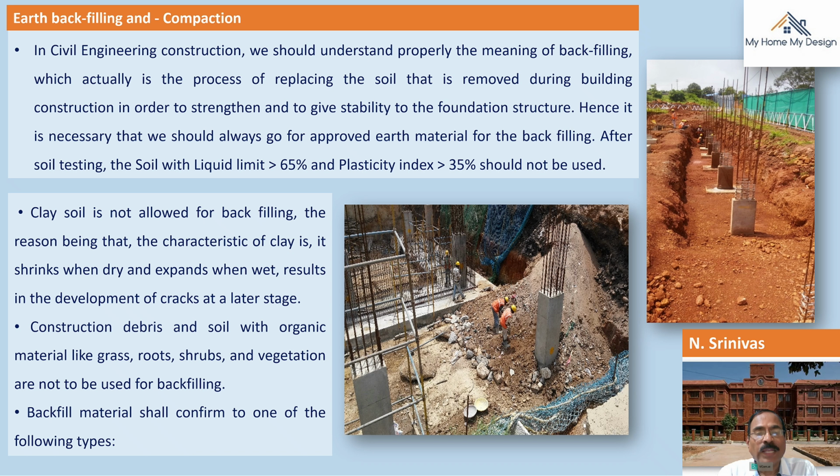Now, clay soil is not allowed for backfilling. The reason being that the characteristic of clay is it shrinks when dry and expands when wet, resulting in the development of cracks at a later stage. Yes, what is this clay soil? In Kannada, we call this clay soil as JD Mannu. It shrinks when dry and expands when wet.